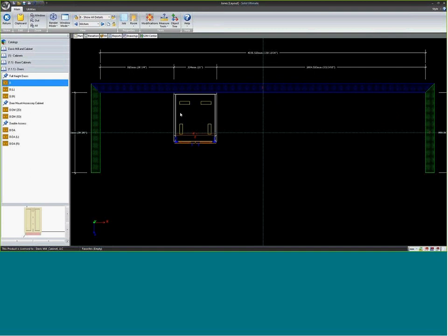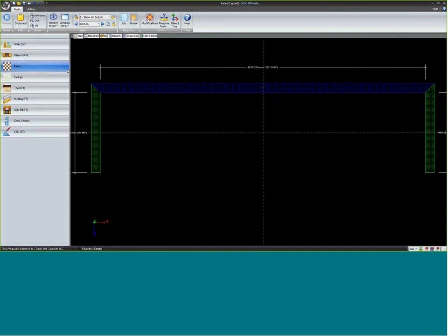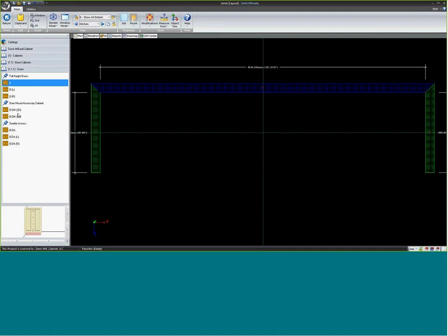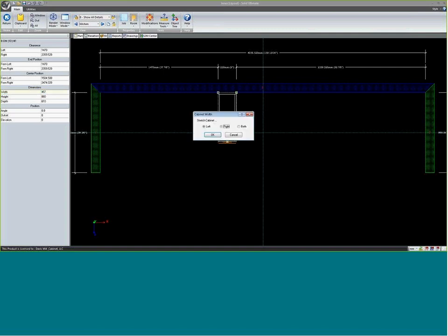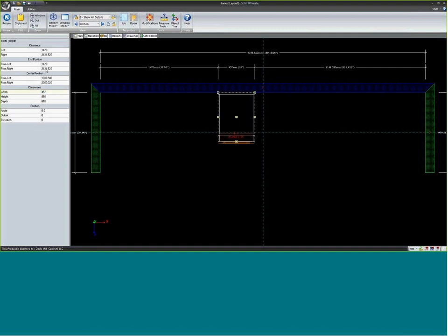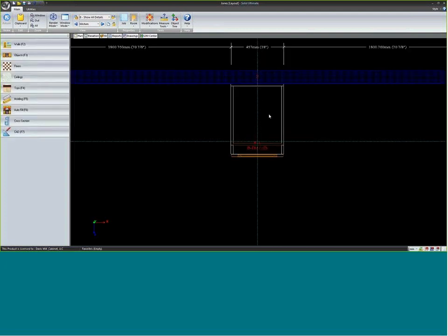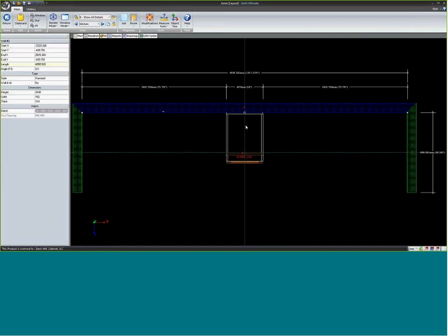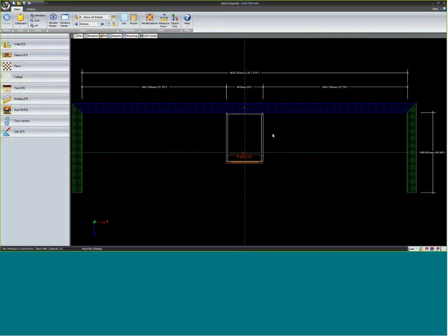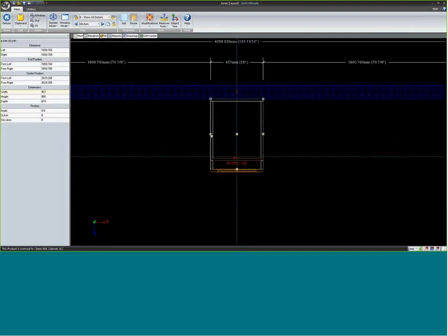Remember we put a trash pull-out. In fact, let's use a trash cabinet. I'm going to come back in here to the objects to a door mount accessory cabinet, single door. Let's make it 18 inches wide. Now, I could come in here and put 0 clearance on this wall and then divide by 2 to center that. So I can use my mathematical formulas in here to center things. But it's a one-time calculation. If I change the width of this wall, this cabinet will no longer be centered on the wall.